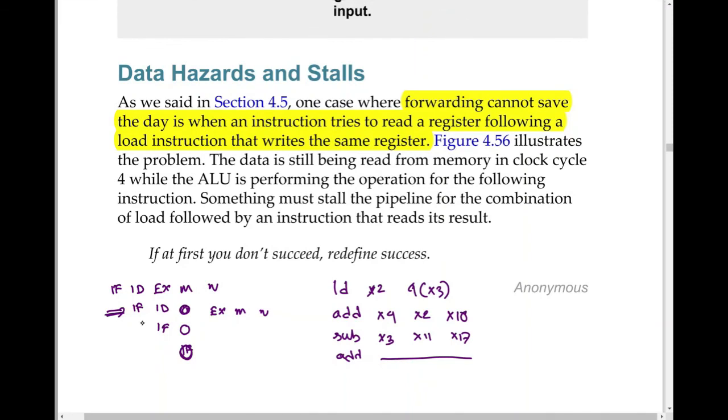If we are applying a stall, just remember the complete data path of the pipeline. If you apply a stall in the execution stage, what is on the left side of the execution stage? Decode and fetch. So it cannot perform any new decode, and it cannot perform any new fetch. That's why it should all stall here.